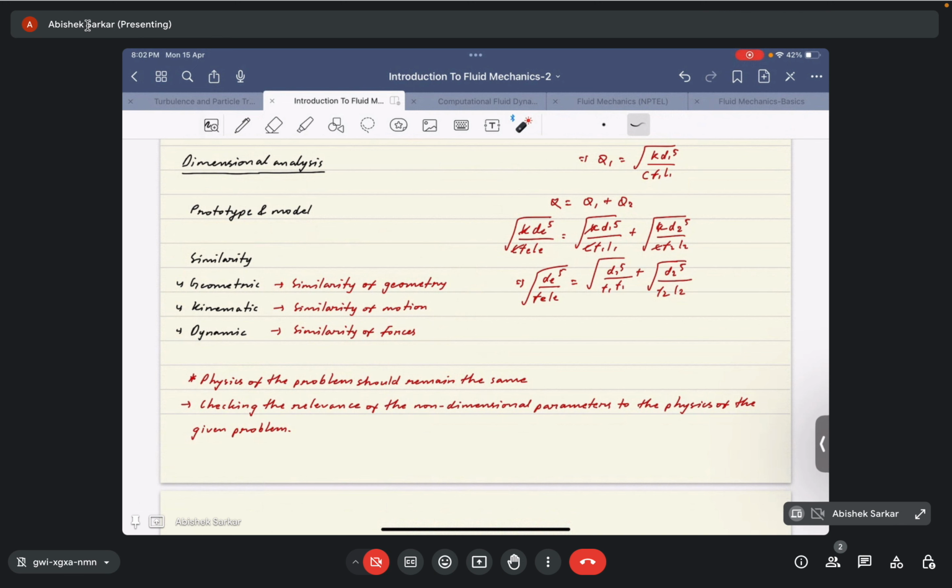By looking at it, you can check the parameters that you have in your head. It will depend upon the incoming free stream velocity, because that's the parameter that can be changed, that is in our control. Then we can change the fluid that we are going to use, so we have control of the kinematic viscosity of the fluid. Moreover, we can also control the length of the plate we are going to use.